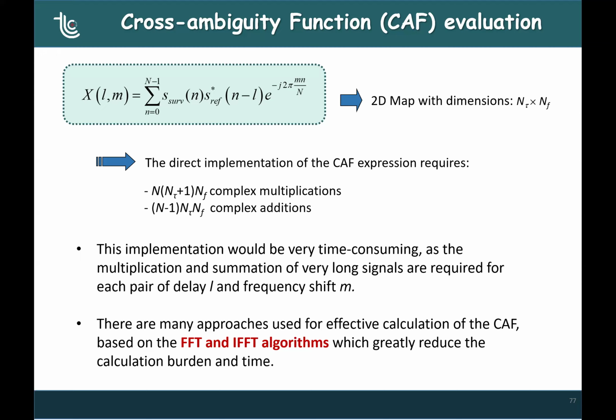Actually, this is the normal way that in many cases is applied for making efficient convolutions. So generally we pass to the frequency domain, we calculate the product of the Fourier transforms, and then we invert the Fourier transform to go back to the time domain. So something similar is performed here in the calculation of the ambiguity function.